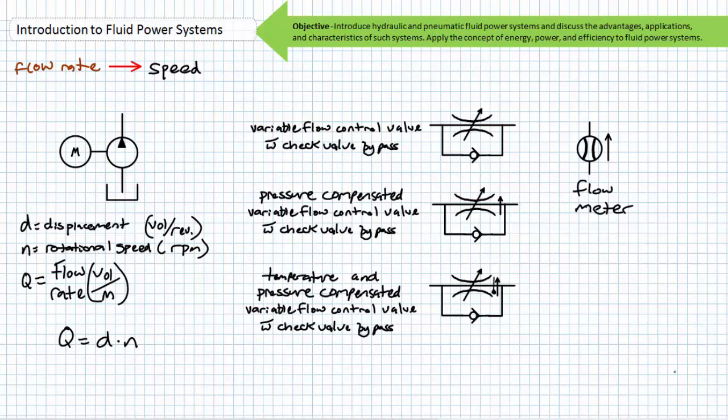Additionally, some flow meters must be vertically mounted such that the flow goes upwards through them. A flow meter intended to be mounted vertically, in to out, bottom to top, won't read accurately if it's mounted on its side, upside down, or if the flow is routed through it backwards. A needle slides up and down on a scale, indicating flow rate in the desired unit.